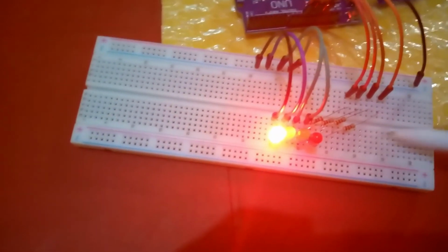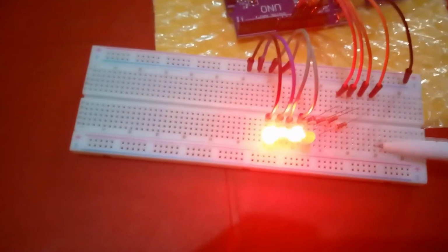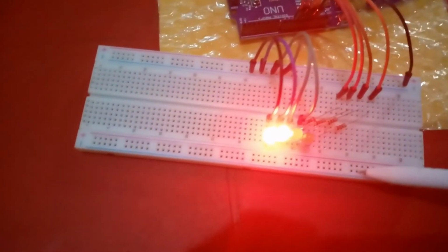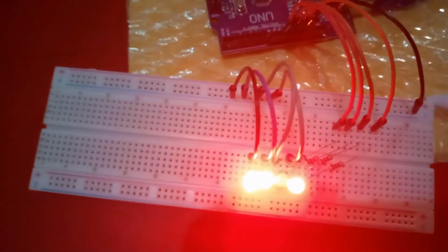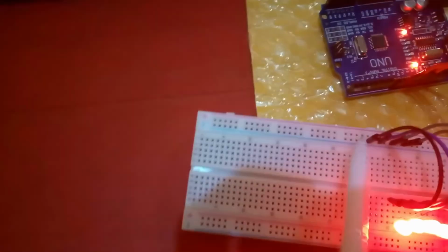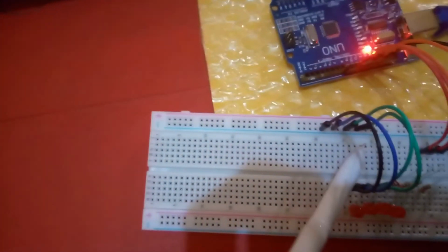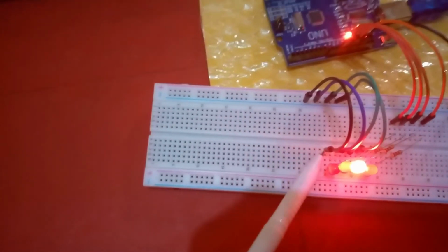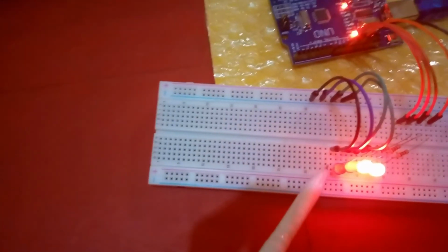So basic knowledge of how the breadboard works. Let me just explain that. For the rows, they are not connected. That is over here. The rows are not connected, but the columns are connected. But in this place where I connected the ground, the rows are connected, but the columns are not connected. That's why you can see I arranged all this in a row. But in terms of the LED connecting with this to the ground, I arranged them in a column.